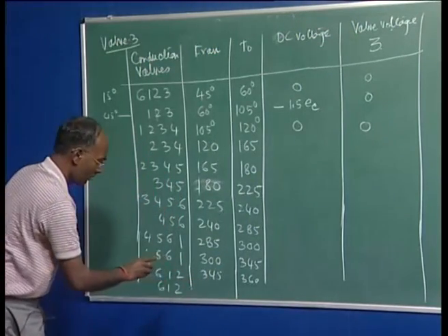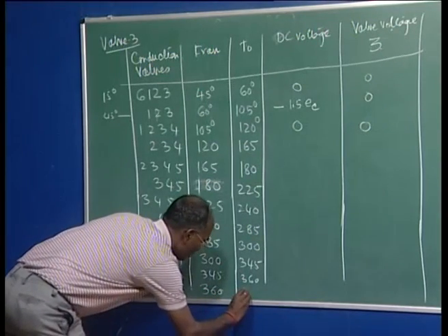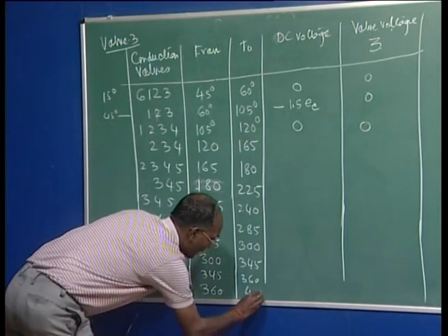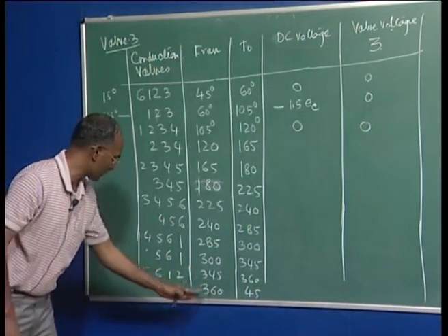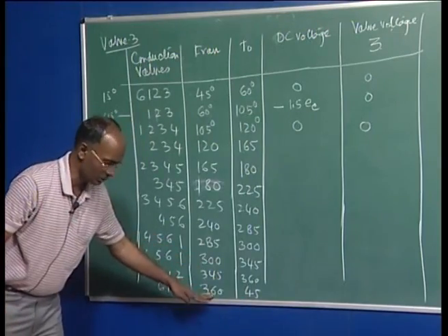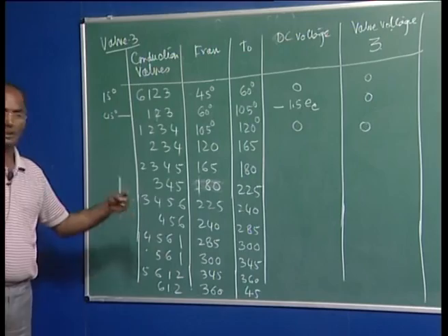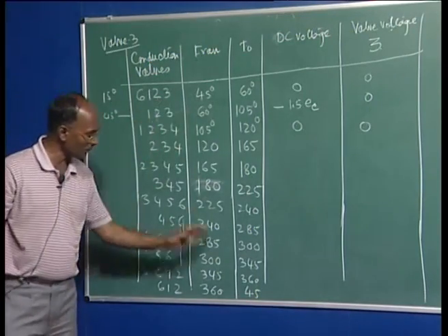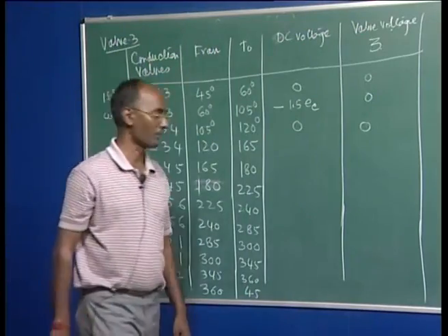Check whether there is any mistake. So, it is 360 to 45 degree, again we are back here, or you can add 45 degree here, because this is 0, and again you are going from that. So, we are just coming back. You can also see that if you are making any mistake, if you are not getting 360 degree, it means there is some problem somewhere.